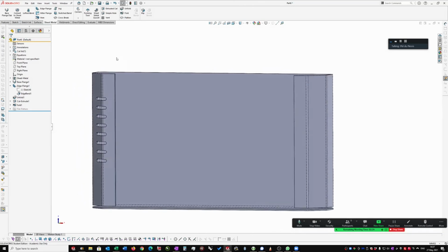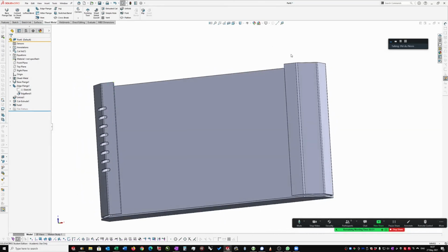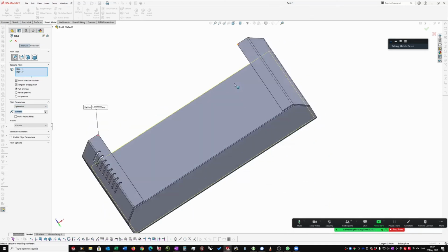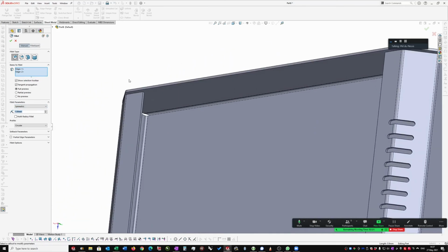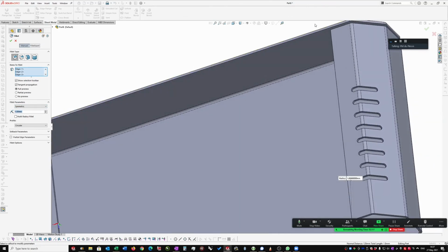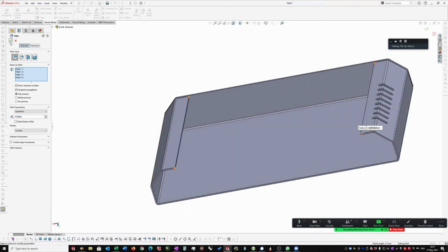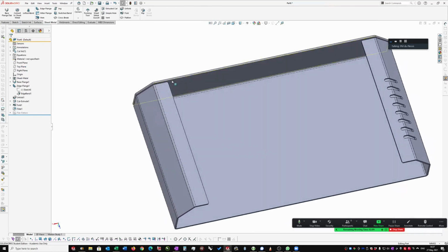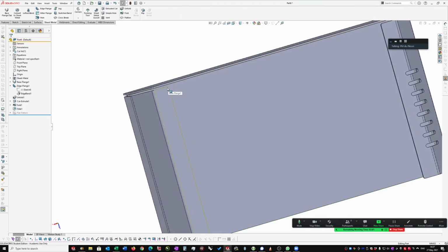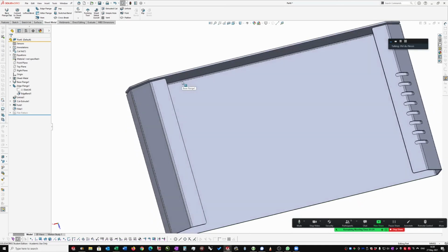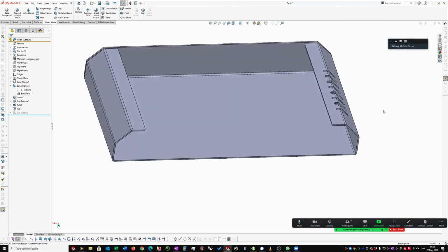Okay, and then the sheet metal has the same functionality as everything else. You can add corners in, or chamfers, fillets. Give that a fillet of 1. I do a lot of sheet metal. I like to fillet all the corners that I can, so that people on the production line don't cut themselves. So I try to find all the corners and give them some sort of radius. It also helps in laser cutting, because it's easier for a laser cutter to go around a corner than to meet a sharp edge. So it actually speeds up the laser cutting slightly.